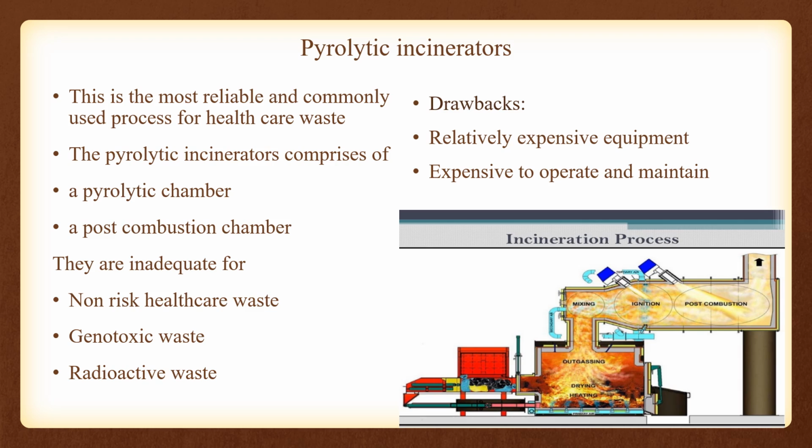The gases produced in this way are burned at high temperatures, that is from 900 to 1200 degrees centigrade, by a fuel burner in the post combustion chamber, using an excess of air to minimize smoke and odors. The pyrolytic and the post combustion chambers should be of steel with an internal lining of refractory bricks resistant to corrosive waste or gas and to thermal shock.